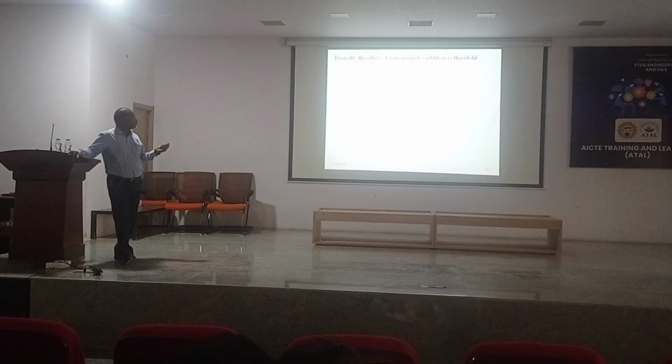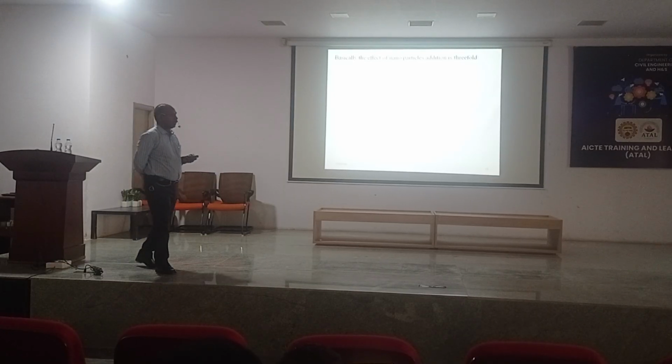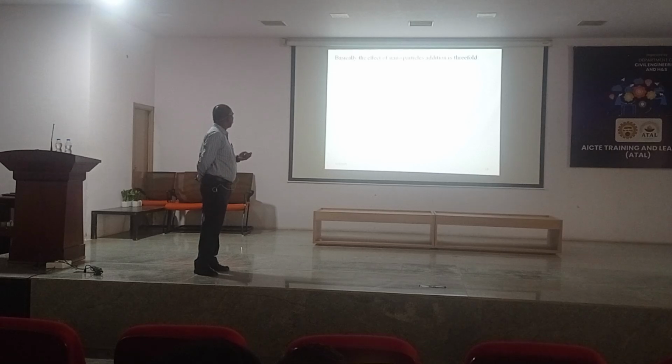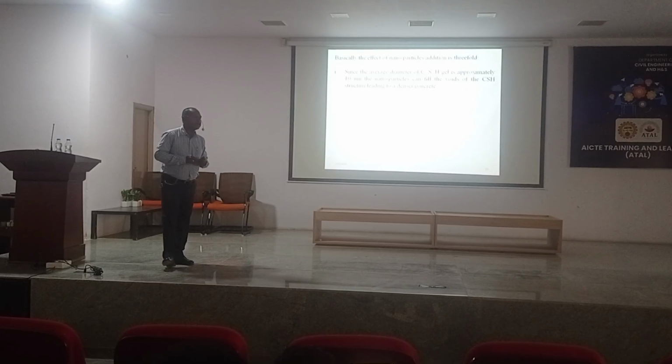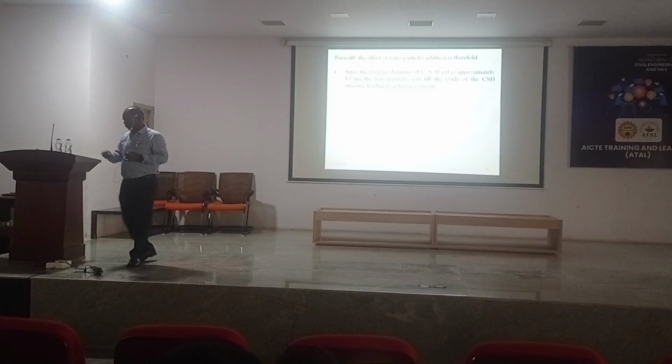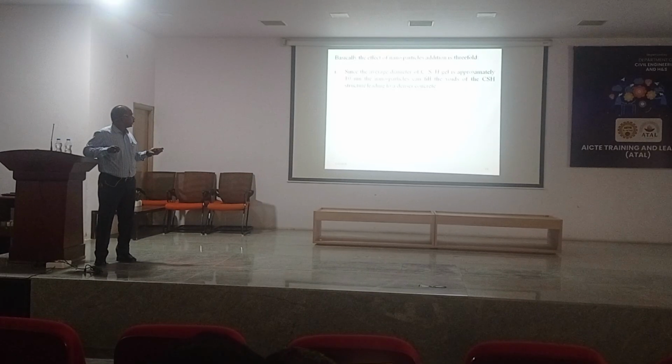Okay. Basically, the effect of nanoparticle addition is threefold. That means there are three mechanisms. Okay. First mechanism is the average diameter of calcium silicate hydrate, CSH gel, is almost 10 nanometer. Okay. The pores are that much nanometer.